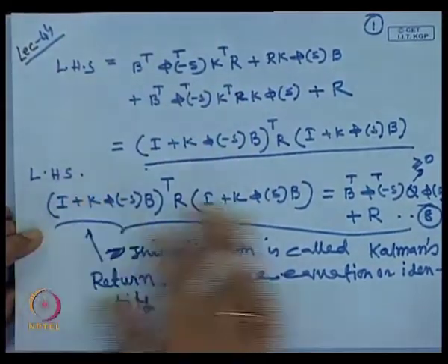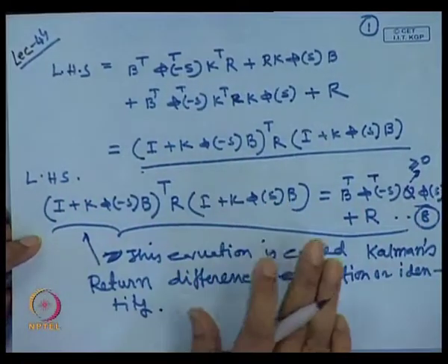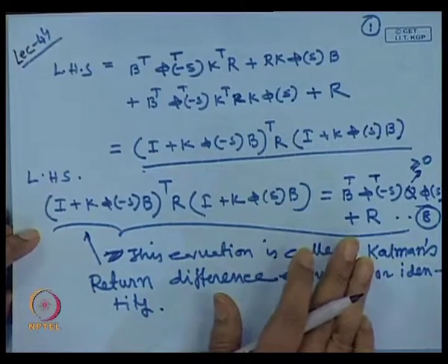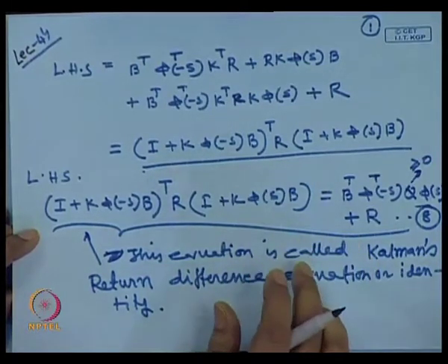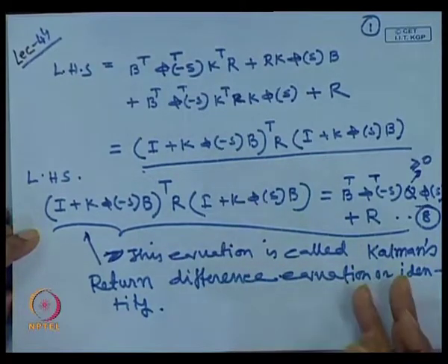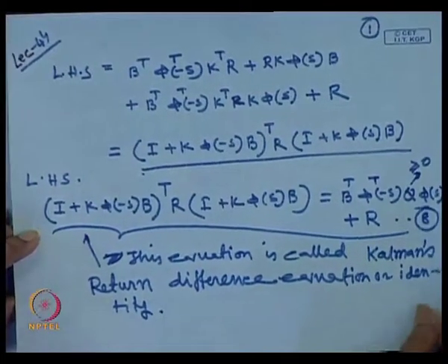This is the algebraic Riccati equation from which we got this expression. We need it to solve for the gain of the controller, because we need the value of P, and P is the solution of the algebraic Riccati equation. So, after getting this, we will now define the gain margin and phase margin of the LQR control systems. Okay. So, we can write from equation 8,